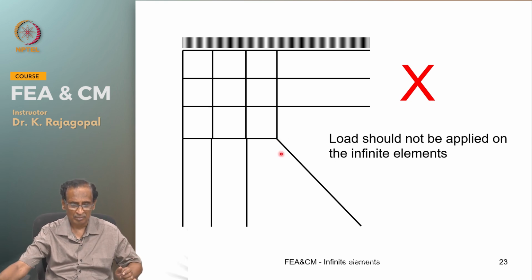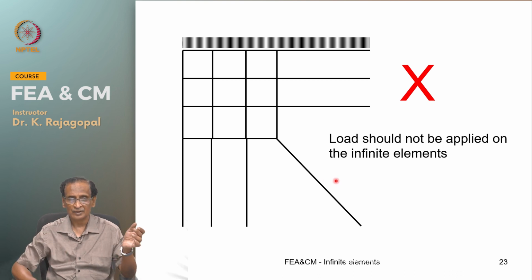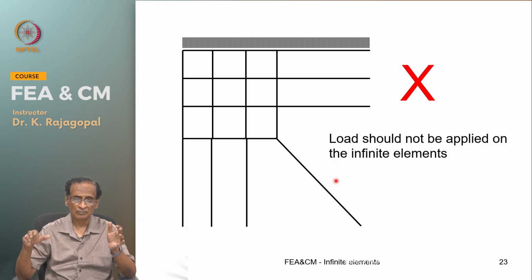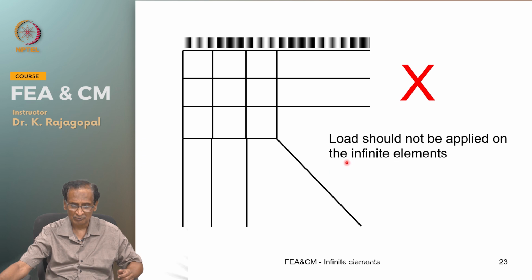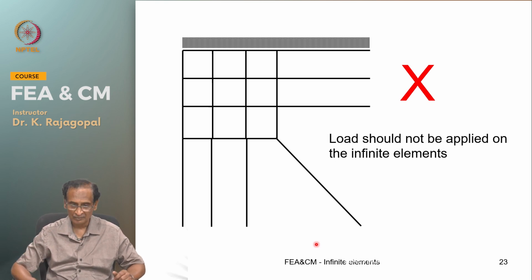But by experience it is seen that by simply moving this line at 45 degrees, using our one dimensional mapped infinite elements, we should be able to represent 2-dimensional infinity. See here, if the local direction is something like this, and for this the local direction is something like this, that shows that you have infinity in both ξ and η directions.